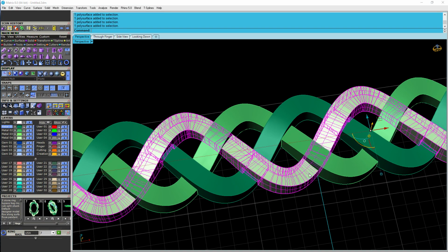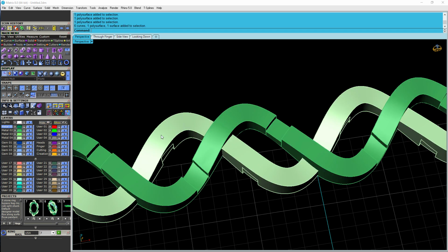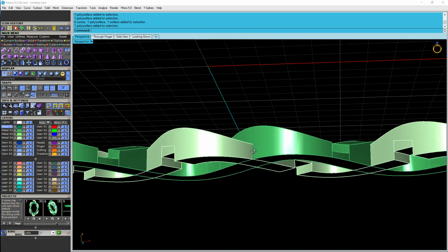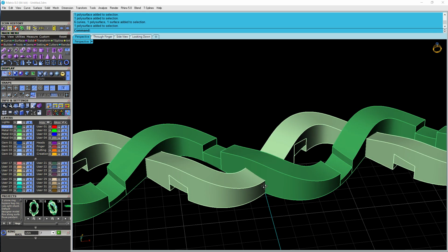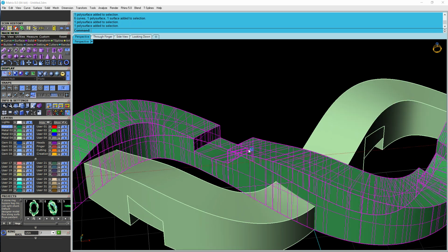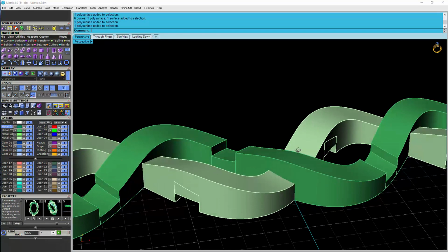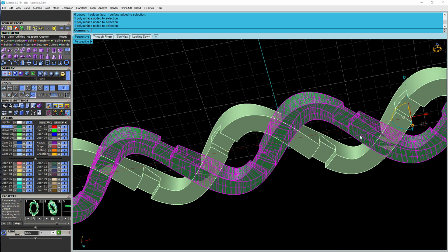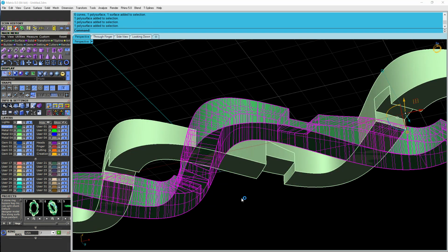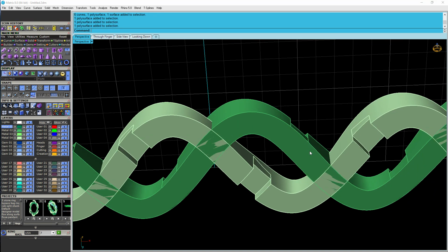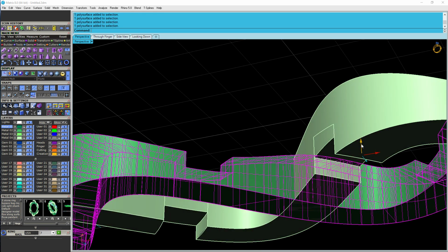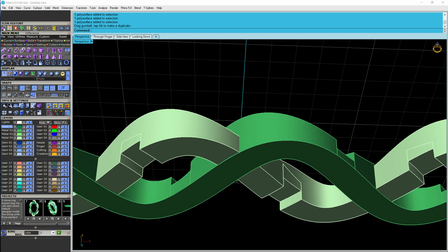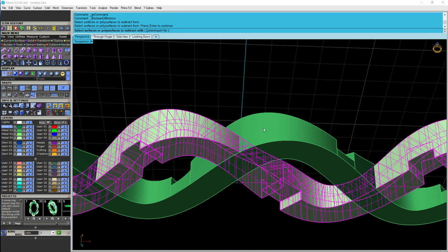Alright, now we need to split this guy up, because we can't have anything in this section here. That's going to be that one solid bottom section. Oh, actually, we're going to split this one at this section. All right. So let's say probably want to move it down first. Anytime you have that coexisting surface like that, it tends to cause issues because the Boolean operation doesn't know what's the inside and outside at that point. So now Boolean difference, we're cutting that with this.